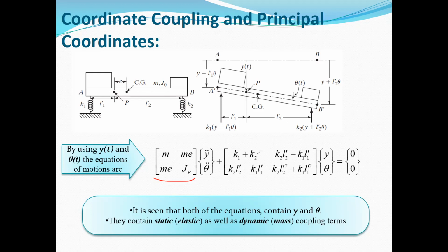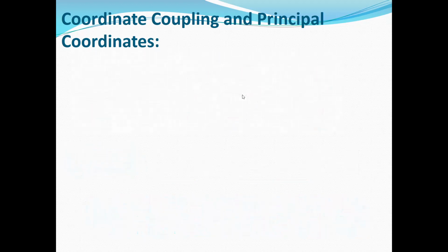So definitely there will be another coordinate system that, by changing to those coordinates, we can vanish the elastic or static coupling in our equations, and we can find a coordinate system under which we will have two uncoupled or two independent ordinary differential equations, and you can separately solve these equations and obtain the response. Okay, so we can draw some conclusions from these points.